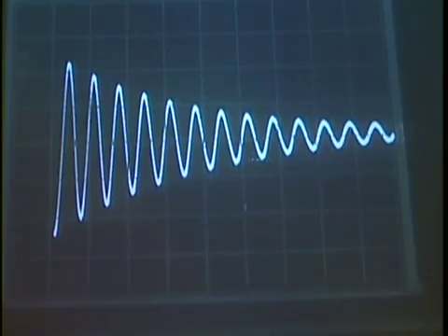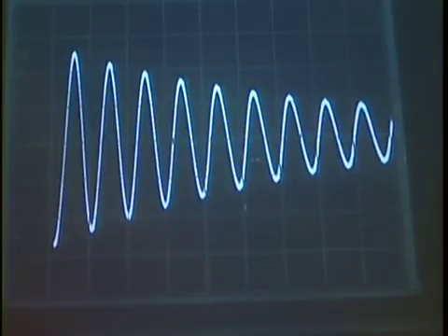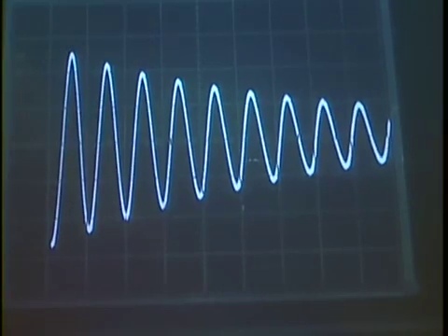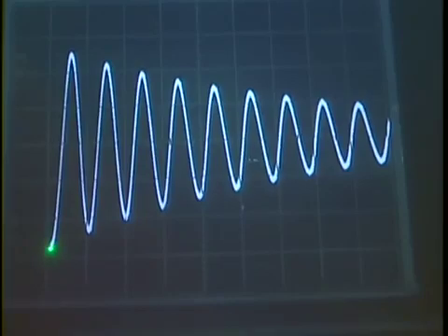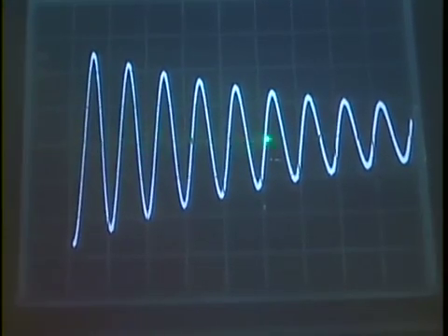If now I change the self-inductance to 100 millihenries, then the frequency goes down from here 2906 to 2055. The Q goes up, and now you have to wait 8 oscillations. So Q is 0 on the left side of the bottom. This is again fully charged, Q max.